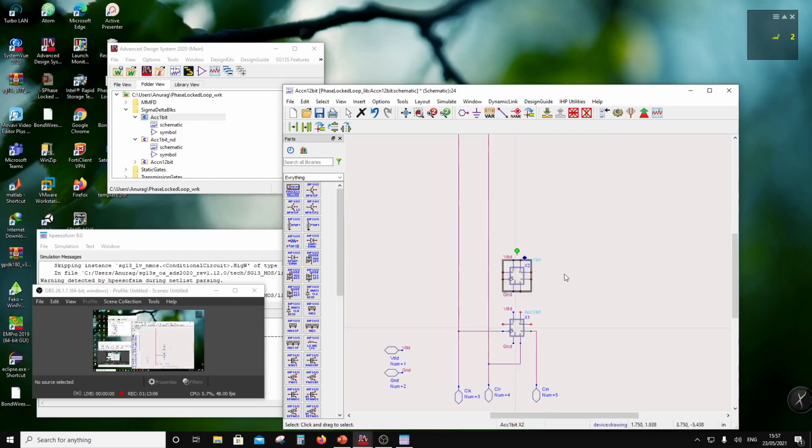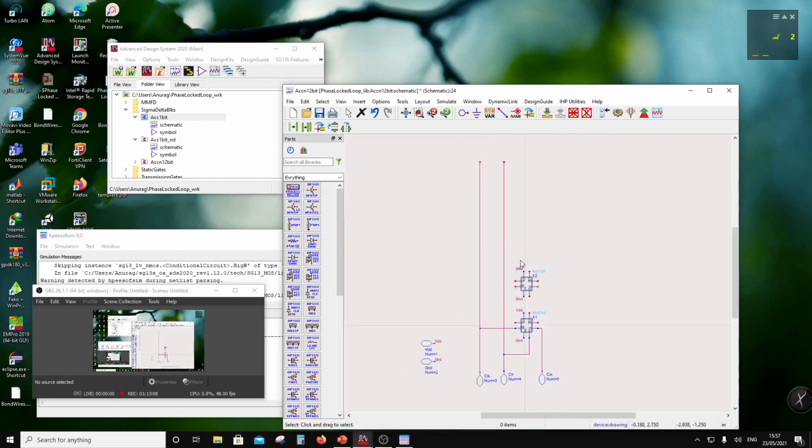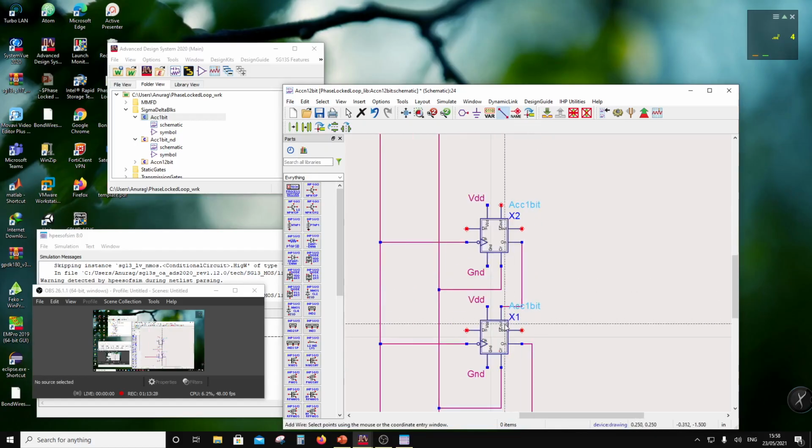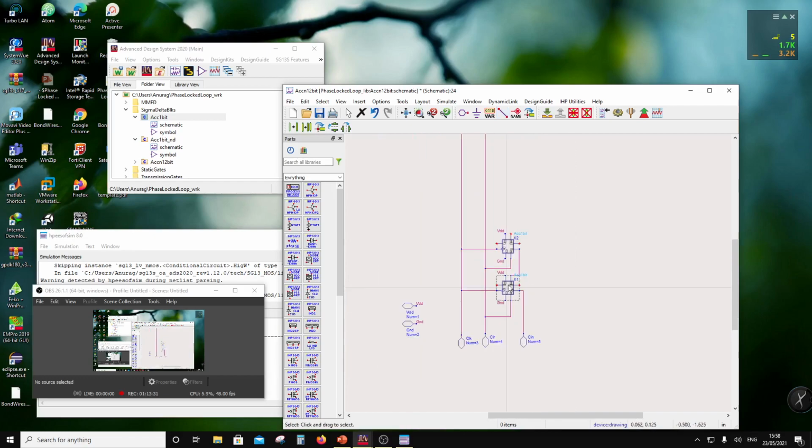Okay. So here, I have clock and clear, right? So here the C out will go to the C in. Okay, so this is C out and that's C in. Done. And then I'm going to repeat this block. Okay, so I'm going to repeat this block again and again. So this is 3-bit.